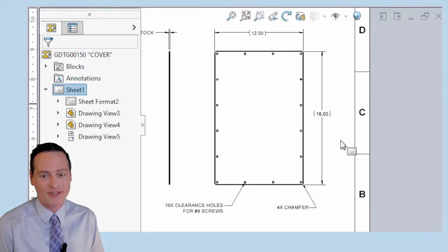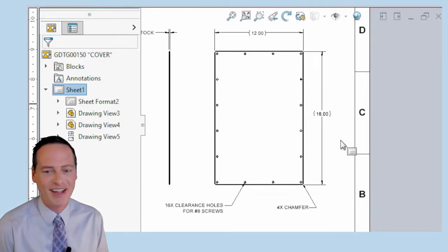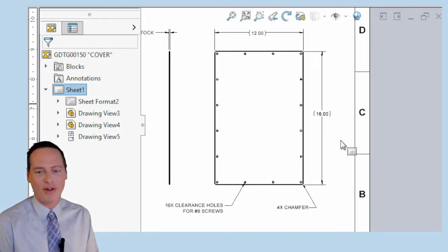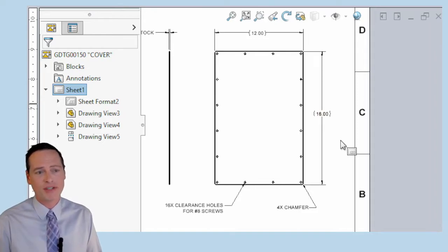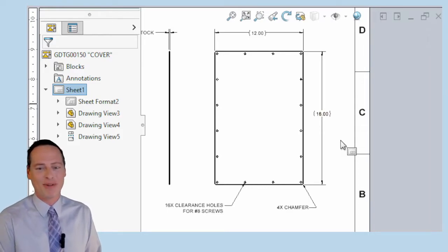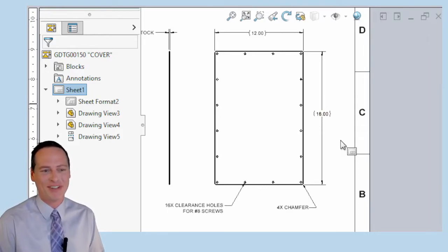Is that wrong? It's not clear. This is not a well-defined drawing, and in the name of simplicity, it actually is going to cause a lot of people to scratch their heads and wonder what the real meaning of these tolerances is, especially since designers will know that in a part like this, there are secret tolerances, secret requirements that are built into this.